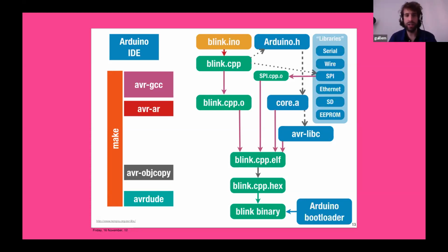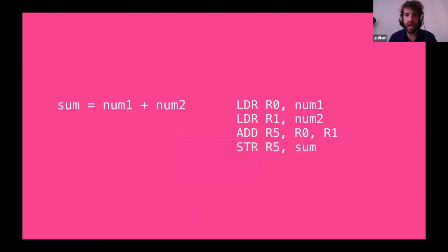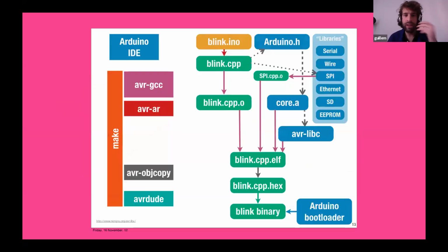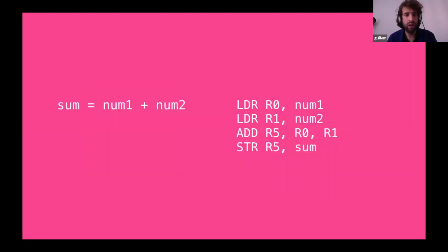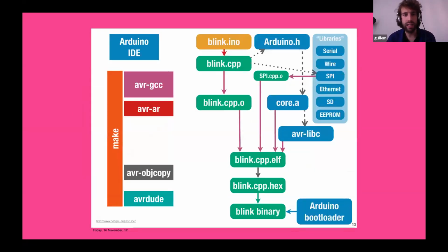That's why when you compile, you need to select, I want this for an ESP32, I want this for a NodeMCU, I want this for a Mega 168, because depending on the chip, the instructions it understands will be different. So these instructions here called LDR or ADD or STR might be different from chip to chip. Some chips may even have an instruction that combines all these 4 instructions into a single instruction. So the compiler takes care of abstracting things for you. And in C or C++ or Arduino, we'll always be writing what's here on the left side. That's the beauty of it at the end.